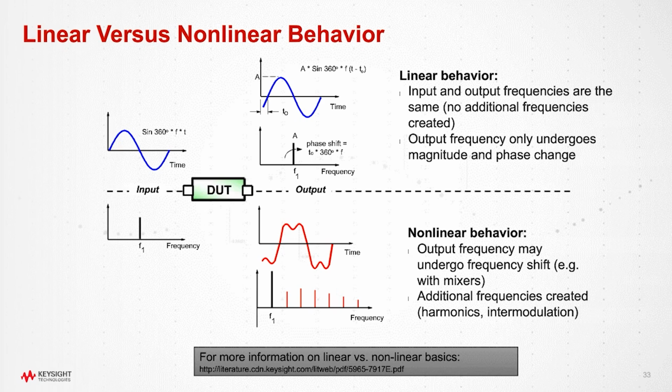But if your device has a nonlinear phase, a modulated signal can have some portions of the signal delayed differently than other portions of the signal. So then that will cause new kinds of errors in the modulated signal. Ideally, we'd like our devices to have linear delay and linear amplitude response, but unfortunately, that's not always the case, and sometimes you have to account for these nonlinear behaviors.